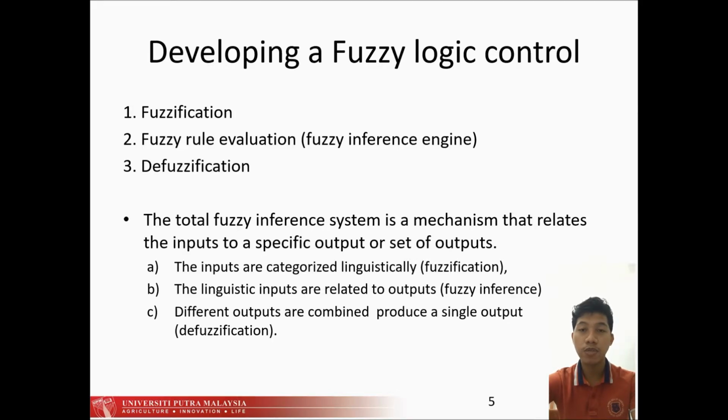So today I will tell about the process. As we know, the PID control has been used, so we approach it with a fuzzy logic controller. The inclusion of fuzzy logic creates many extra design problems, so the approach here is based on a 3-step design procedure. The first one, we start with a PID controller, and then second, insert an equivalent linear fuzzy controller, and the third, make it gradually non-linear.